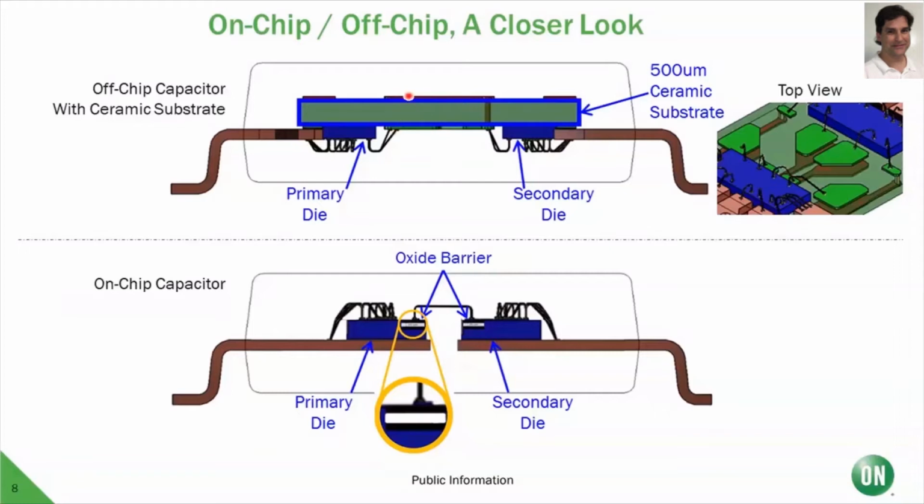We have a transmission line that carries the signal from one side of the device to the other. And then we have a via that carries the signal back through the ceramic substrate. So the distance through insulation is 0.5 millimeters because that's the smallest distance between primary and secondary side contact points. We also have another primary to secondary contact spacing, which is along the surface of this ceramic substrate, and this is 0.8 millimeters minimum in our Digi-Max technology.